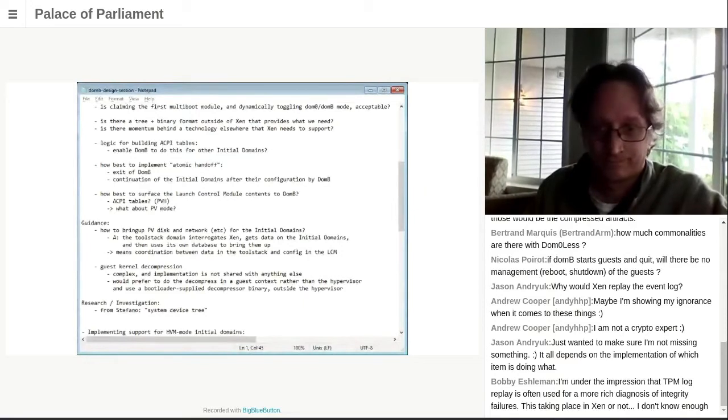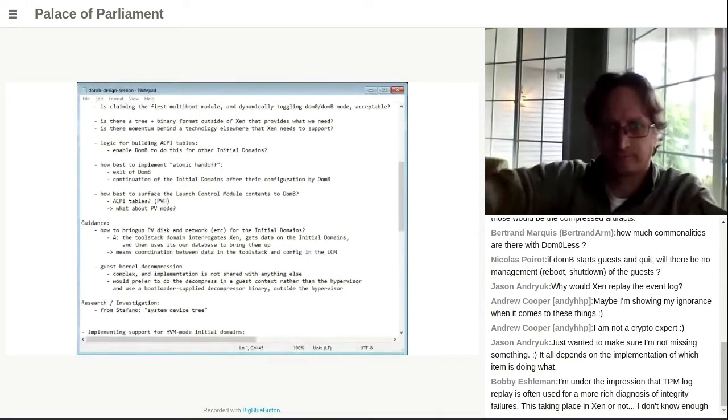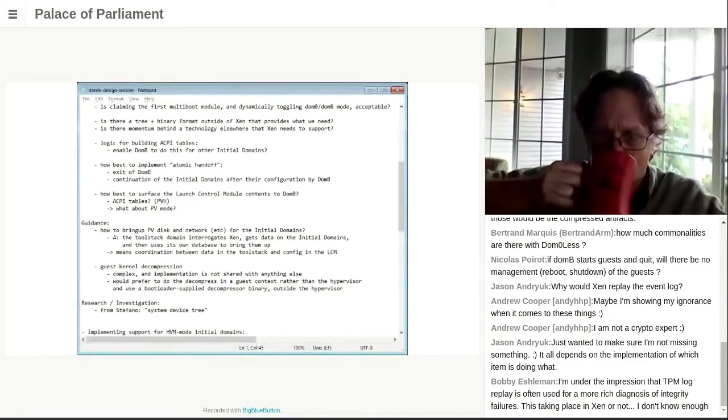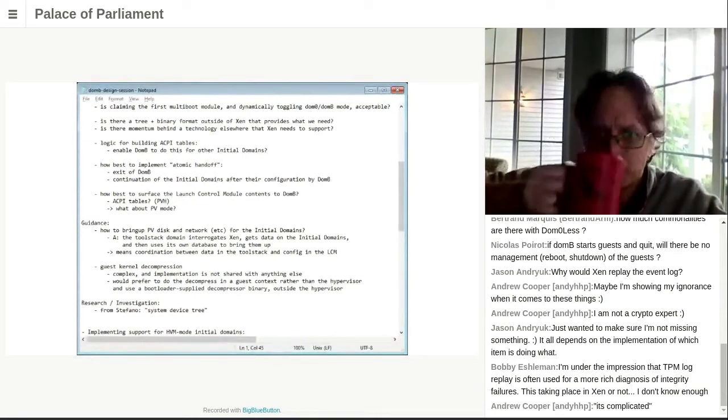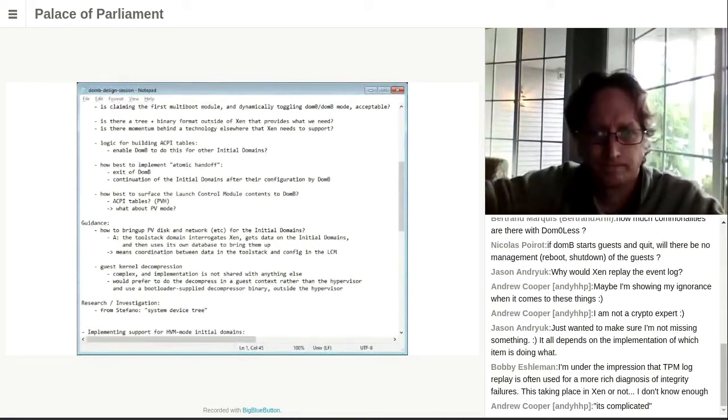I'm here. So, for device tree, I think you have to think about each part as separate. There is a spec to describe the source format, the spec to describe the binary format, and then there is the convention, the device tree specification itself, on how to describe the hardware.